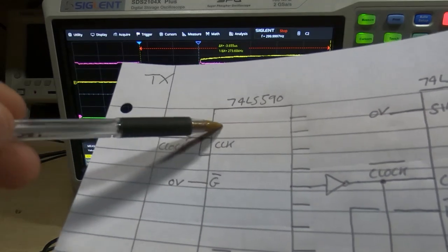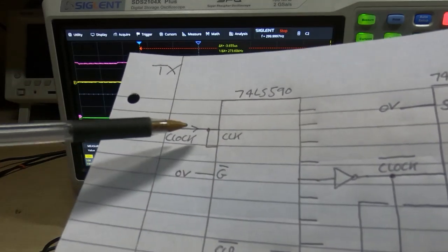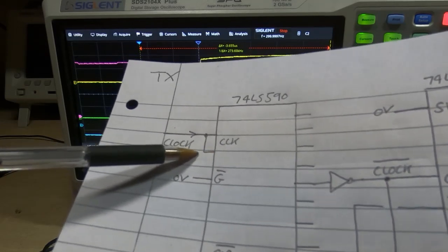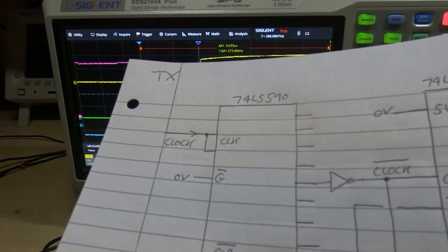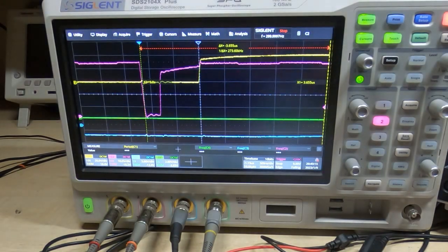We still need the counter to run at 625 kilohertz because that's what gives us our correct baud rate. But running the register clock at 10 megahertz means that it will feed the data through much more reliably. So I'll make that very small change now.